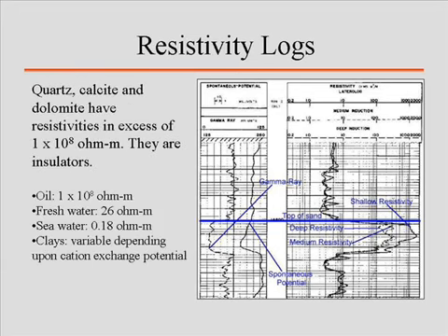And I mentioned I was going to give you some resistivities, and here they are in terms of different fluids and different materials. Oil is a very resistant material. Its natural resistance is 1 × 10⁸ ohm meters. Fresh water is significantly more conductive, so it's down there. Seawater, salt water, is far less than that. All right, and then you'll see clays are variable depending upon what they actually have in them.